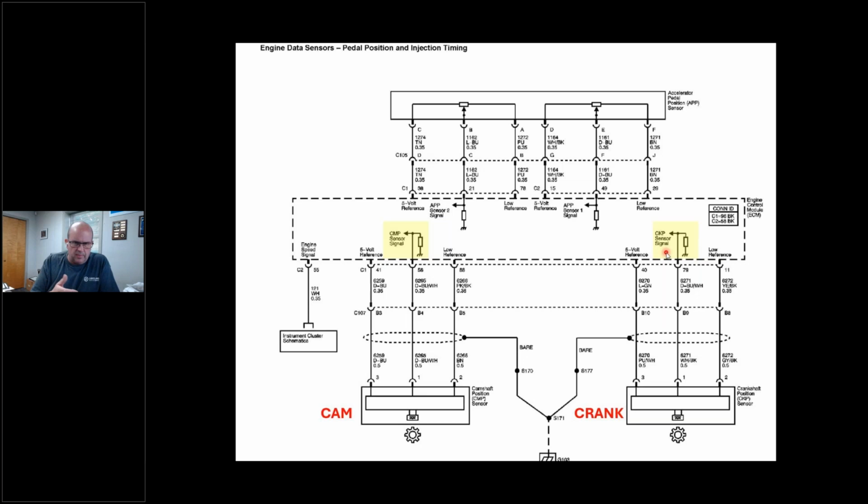I can use the current, but I can't ID cylinders. And I know you'll go online, and yes, I see guys zip tie knock sensors to the fuel injection rail and all that stuff. I've seen that. I haven't done that yet, but the purpose of our discussion today is modern stuff, or pseudo modern. So I'm going to show you this crank sensor because sometimes I might want to get on that to see what the crank is in relation to the cam.